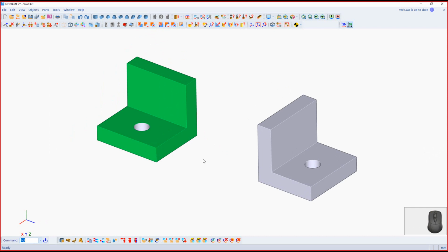Very good. Now that I have the hole created, I will add some fillets. For example, I have a couple of options also. Continuous edge, single edge, a patch outline. For this particular example, it's basically the same. So I can do this thing here. Let us say a 5 mil radius.